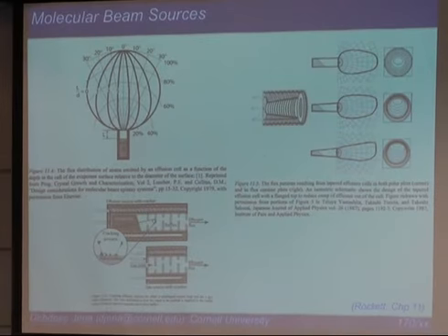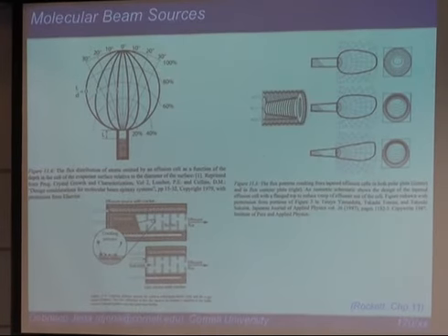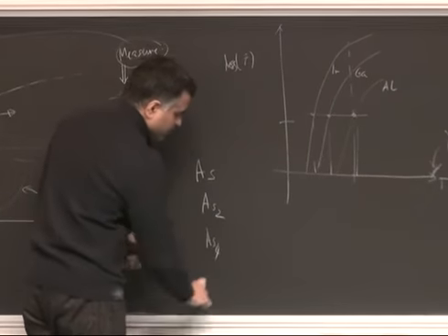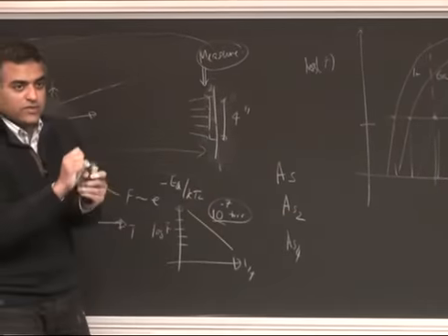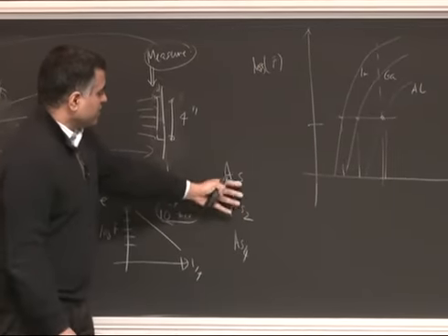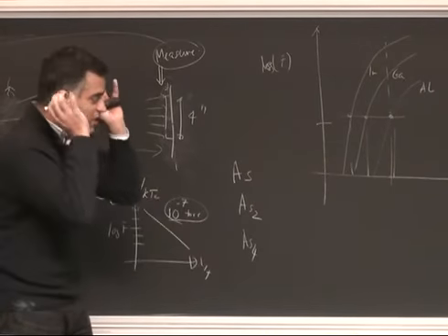There are some elements, actually arsenic is a good example. Arsenic, when you try to evaporate it from a crucible like this, arsenic comes in many forms. It has obviously the atomic form. You would like to have that. But it will come as a dimer, two arsenic atoms together. This is a monomer, dimer, tetramer, and all that. So you'll have all varieties of arsenic, which will be formed. It will be a cluster of arsenic atoms. Right? And typically, you want to be either monomers or maybe max dimers. You don't want the higher clusters when you want to deposit it there.